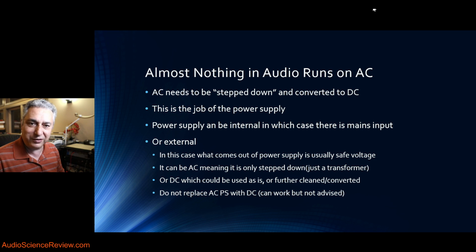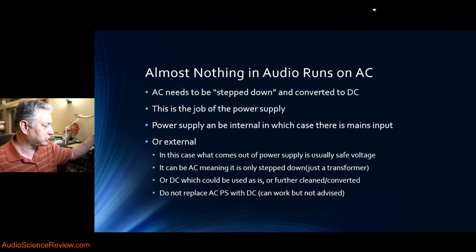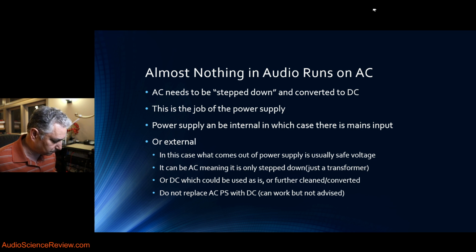A lot of audiophiles are anxious to quickly change their power supply for a better one. Fine, if it's a DC one, you have many choices. But the moment it becomes AC, you cannot change this with anything else because this is not a complete power supply. It's just a step-down transformer. The rest of the power supply is internal.